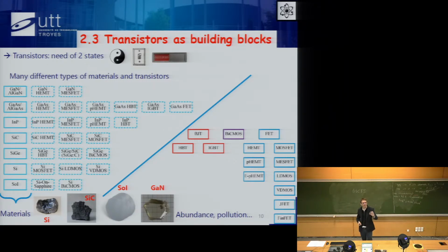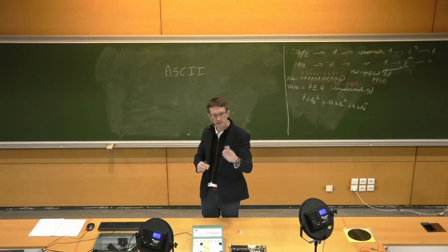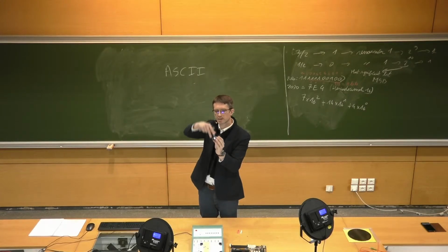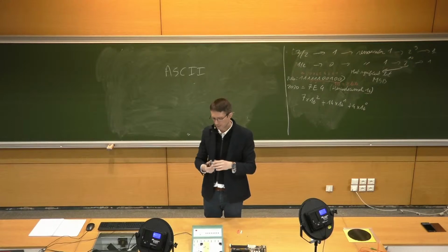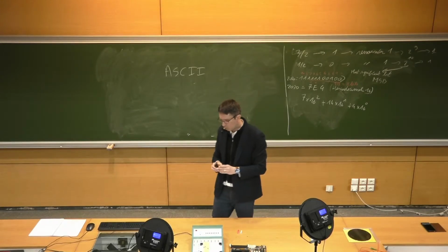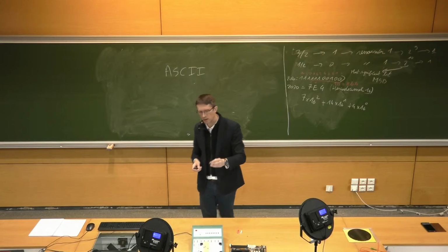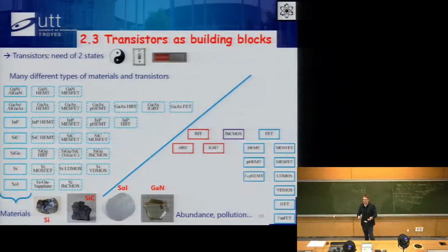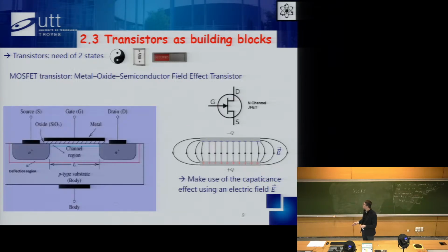So here you have a piece of silicon. It's a silicon crystal that has been grown like this, and then it's been sliced. You can see how it's been sliced into thin substrates, or wafers. In this case, it is about a 2-inch wafer. And this will basically give you the basic material for your transistors. It could be, for instance, this P substrate, because the reason we use these materials, silicon especially, is that you can dope them at will: N-type, P-type, N plus type, or N plus plus if you want to extra dope it, and so on and so forth.